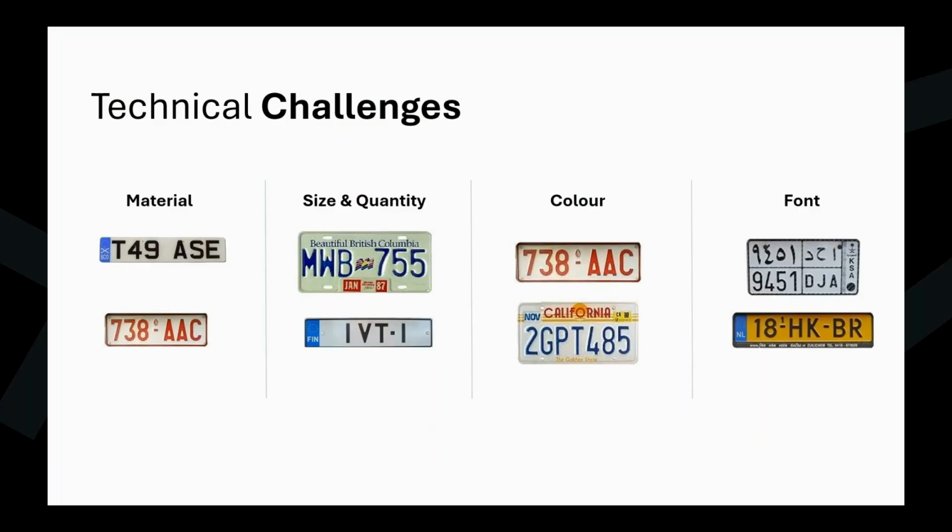The color of the lettering affects the choice of lighting, mainly wavelength, of course. This is because red lettering can reflect light almost as well as the white background that it's usually situated on, which ends up providing very little contrast for analytics to pick up. So in order to counter that, often customers will use white light, which we've got a little case study to look at in a bit.